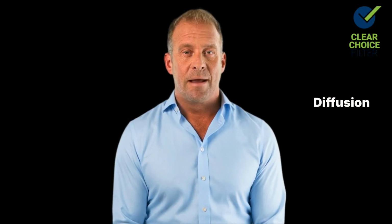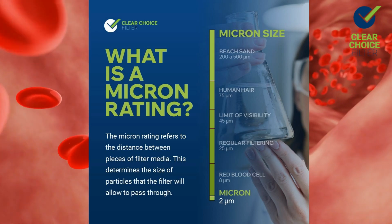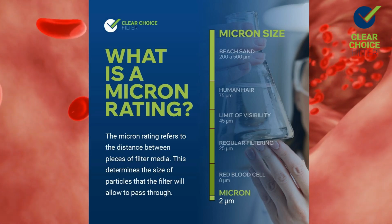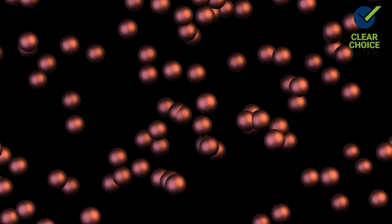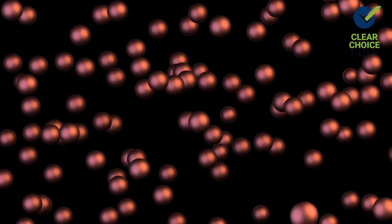Next, we will discuss the mechanism of diffusion. Diffusion is a process that affects very small particles, typically below 0.1 microns. These particles move randomly due to Brownian motion and eventually collide with filter fibers, where they become trapped.